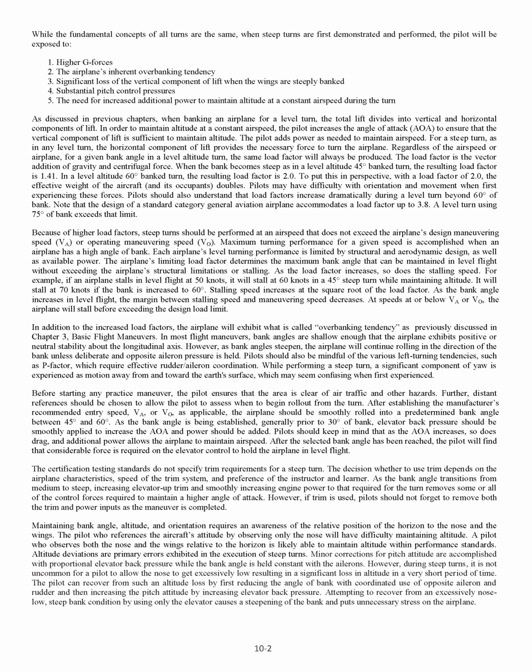The certification testing standards do not specify trim requirements for a steep turn. The decision whether to use trim depends on the airplane characteristics, speed of the trim system, and preference of the instructor and learner. As the bank angle transitions from medium to steep, increasing elevator up trim and smoothly increasing engine power to that required for the turn removes some or all of the control forces required to maintain a higher angle of attack. However, if trim is used, pilots should not forget to remove both the trim and power inputs as the maneuver is completed. Maintaining bank angle, altitude, and orientation requires an awareness of the relative position of the horizon to the nose and the wings.